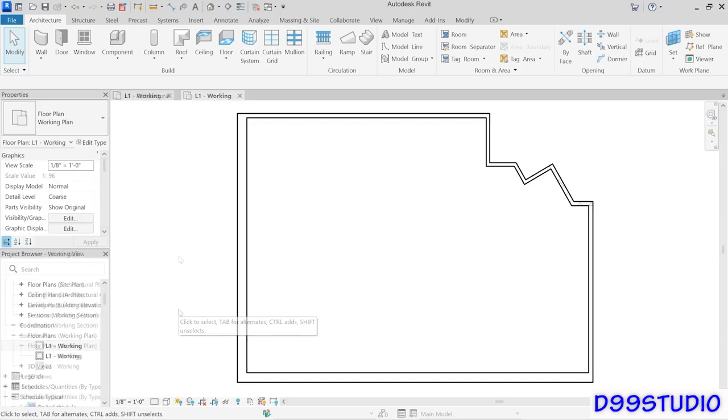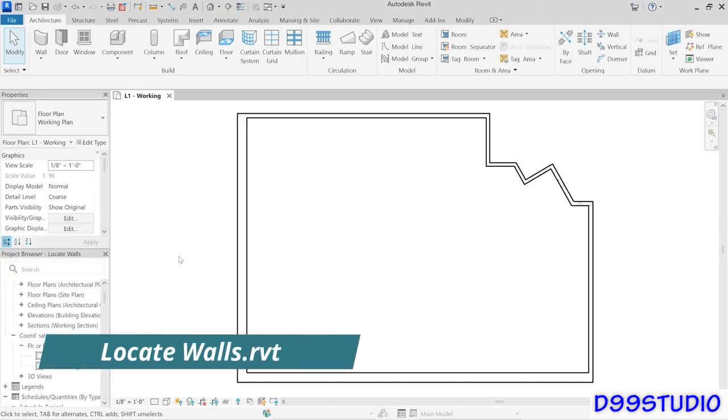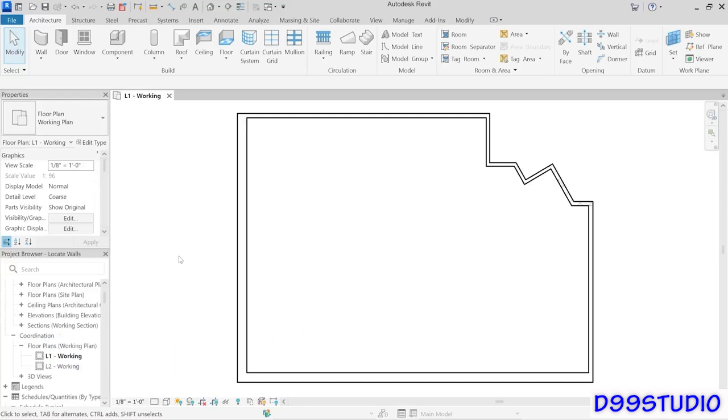Okay, so you can have as many views as is necessary in order to help you perform the task at hand. In this video, we're going to perform the wall layout required for a small 2-bedroom condominium layout. So we're going to work with the wall tool, but we're going to approach it a little bit more systematically and strategically than we did in earlier videos on walls, because here we have a specific architectural layout in mind that we're trying to create. So we're going to use a process that I like to refer to as sketch, then modify, or I sometimes also refer to it as progressive refinement. Now, these are not official Revit terms, but it is an official Revit concept.